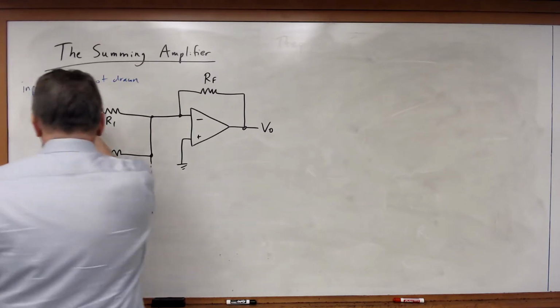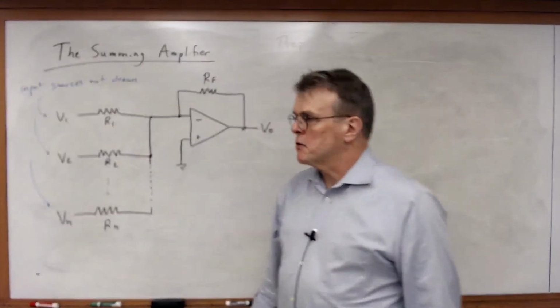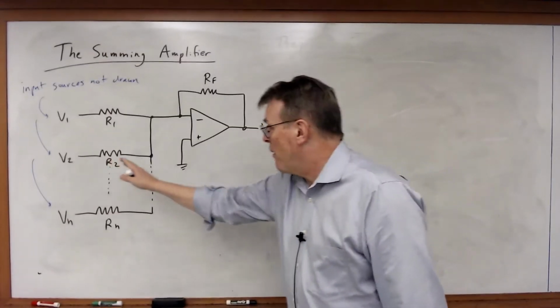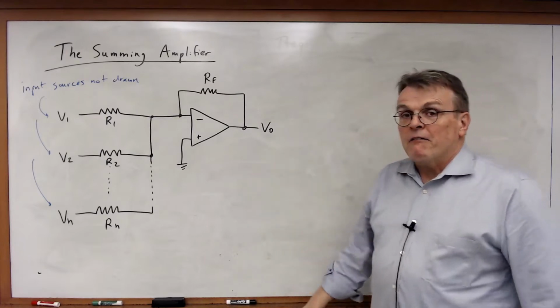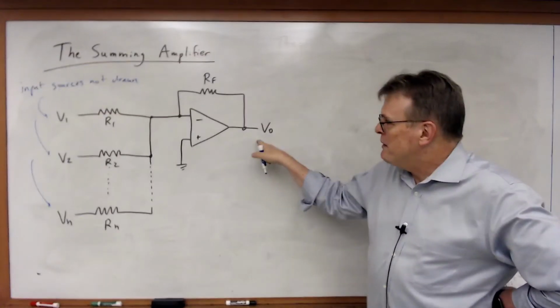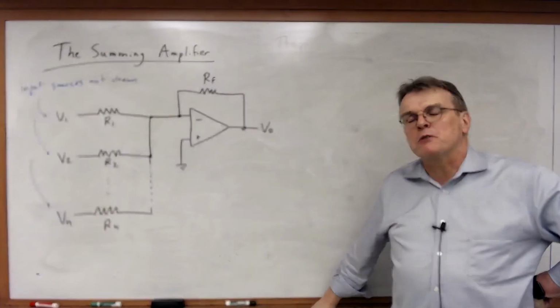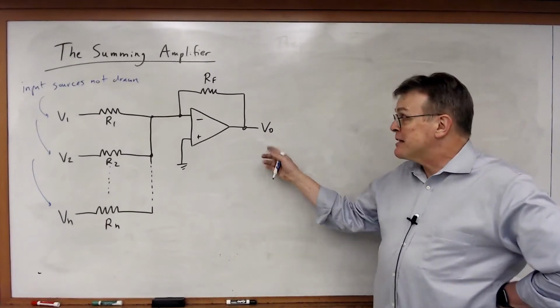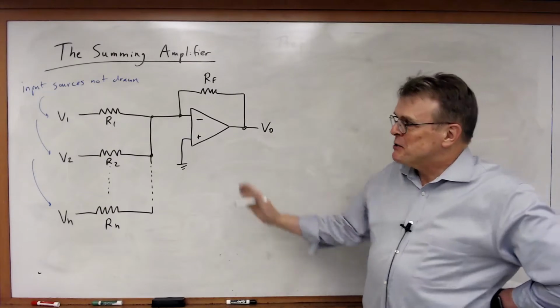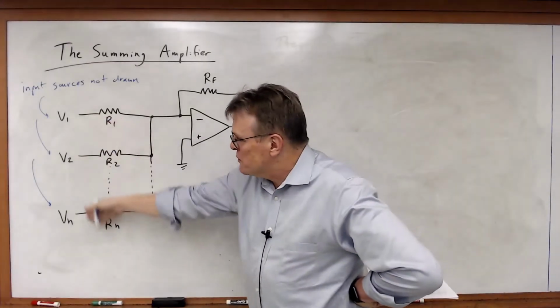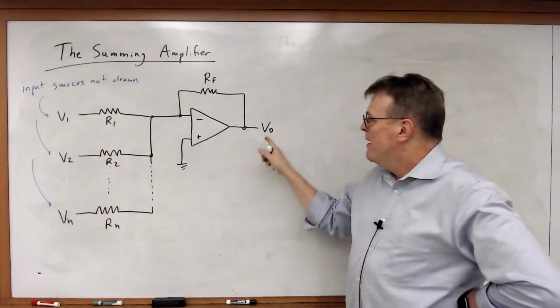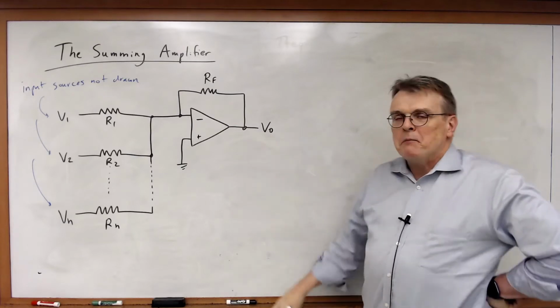So once again, this is a simple shortcut. You see this used a great deal. Now the interesting part is on the right side of the schematic, these are normally outputs. So when I draw VO here, that doesn't represent a source. That simply represents the voltage of that node. So on the left side, there are sources generating those voltages. On the right side, that's simply an output.